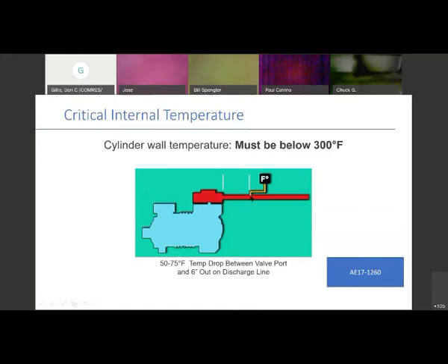And where that derives from is we found over the years that we lose somewhere between 50 to 75 degrees temperature from the hottest point of this compressor. So going with the worst scenario of 75 and adding it to 225, without getting inside the compressor with a temperature probe, we can tell pretty accurately what the temperature of that compressor is inside, 6 inches down the discharge line on this semi-hermetic. 225, add 75 is 300, that magical number where oil starts to break down and things start to cook. It's a nice little way to add something to your tool belt.